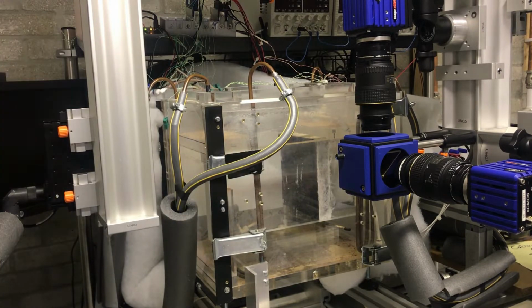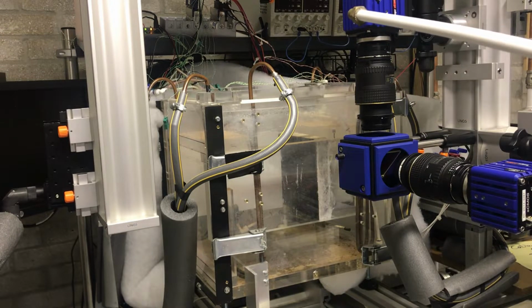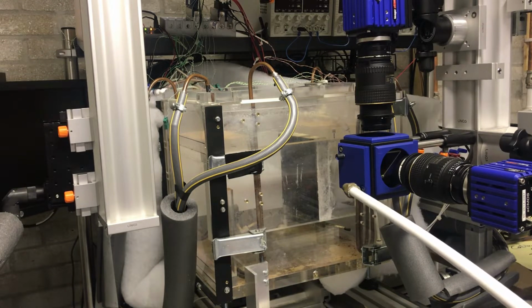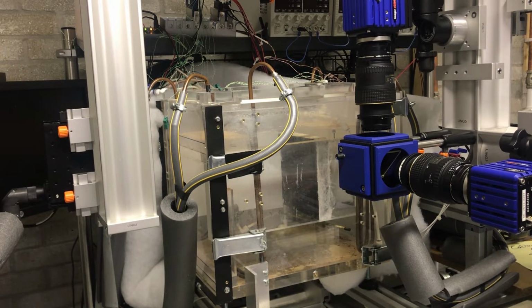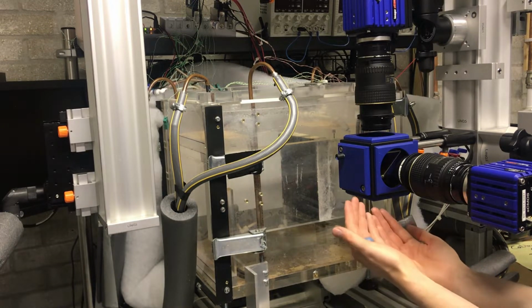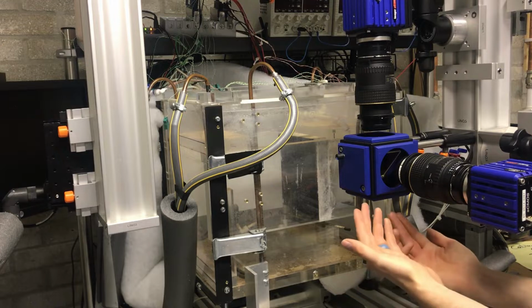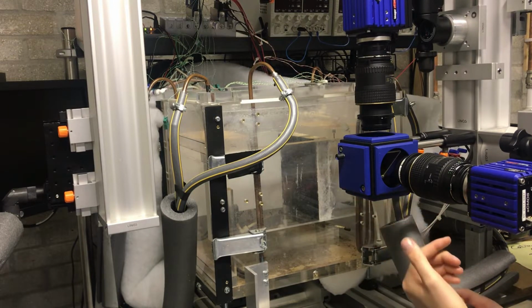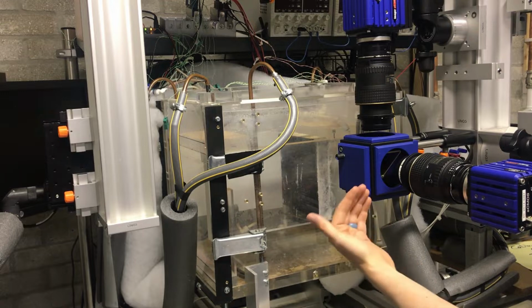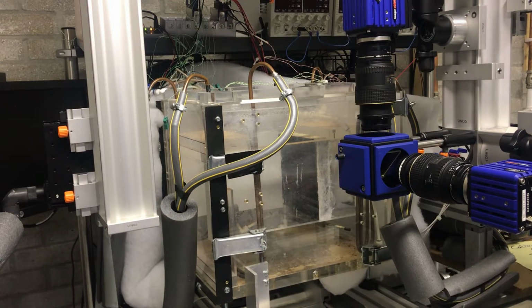So the heater is inside a reservoir and is normally submerged under water, so this tank is filled with water. We've also got two cameras over here, so we've got the PIV camera and the BOSS camera, and the component in between those is called a beam splitter, which is a dichroic mirror. And what that is doing is enabling some wavelengths of light to be transmitted through and into this camera, and other wavelengths are being reflected up into the other camera. So both of the cameras have the same optical axis, or near enough the same optical axis.